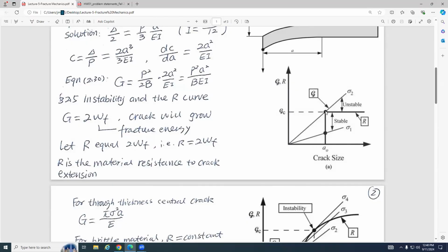That means as long as this exceeds zero, the crack will continue until the whole body breaks. Why? Because the resistance R is constant, and you just break the stability. You break the stability, and you cannot stop. So keep in mind, here R is Gc, right? And we just use the letter R to denote Gc.